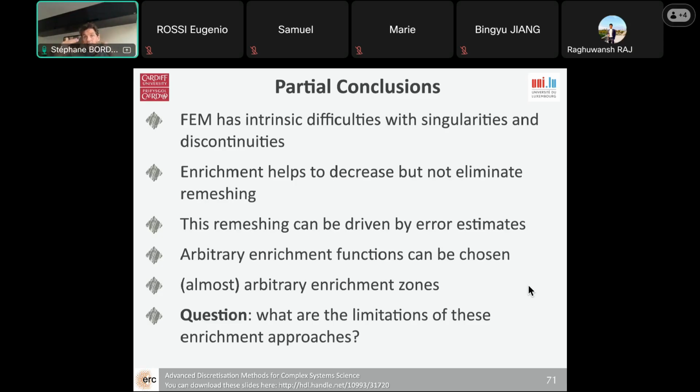If we really wanted to look at that in detail, we would need to go down one scale and figure out, all right, what exactly is the state of the material at that lower scale? Then we would need to integrate it over space, and it would give us an average property at the macroscopic scale, and it would allow us to have a way to propagate the cracks. That's one approach.